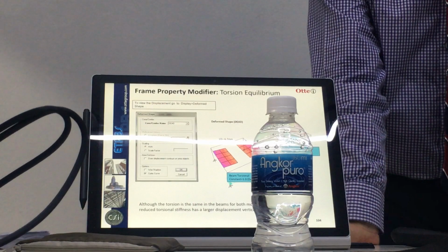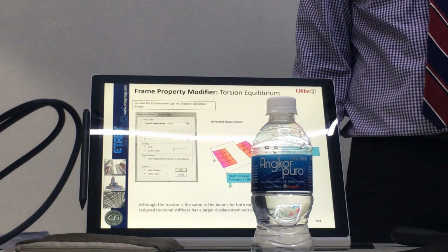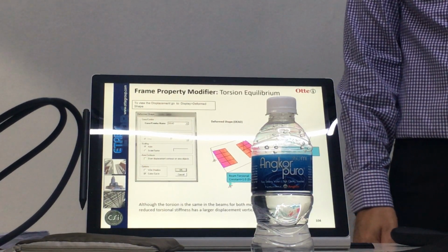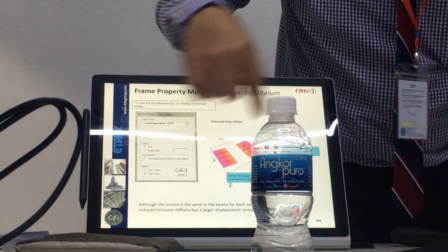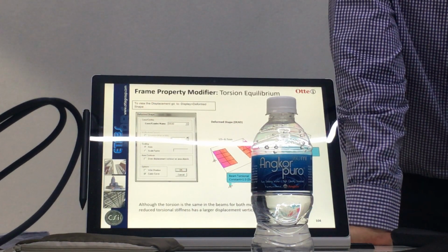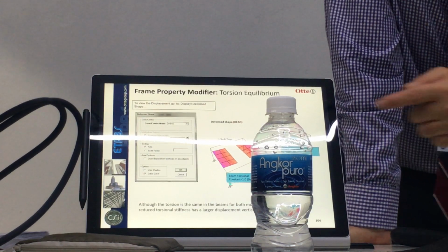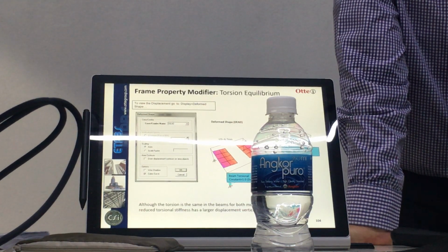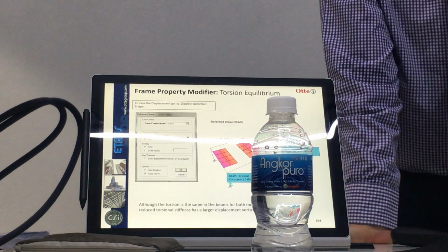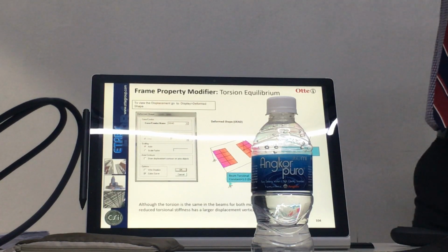It passed. Don't doubt my calculation of my first class honor one from a top university in Cambodia, for example. Yeah? But the thing is, for these two cases, if I ask you to calculate the cantilever displacement at the tip, you will give me the same answer. Right? But numerically, it shows you two different displacements. The reason why, because your hand calculation is based on fixed cantilever. Fixed cantilever, right? Fixed here.